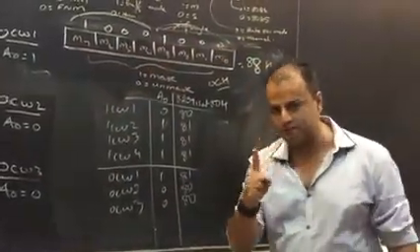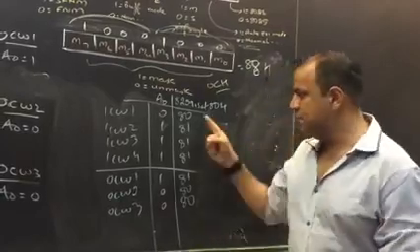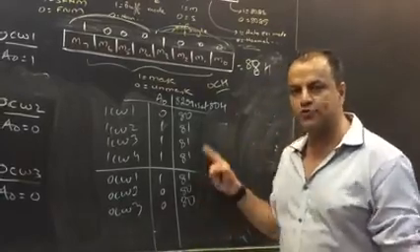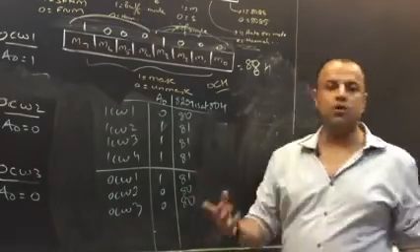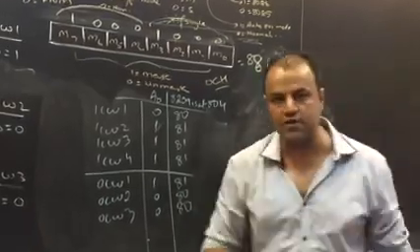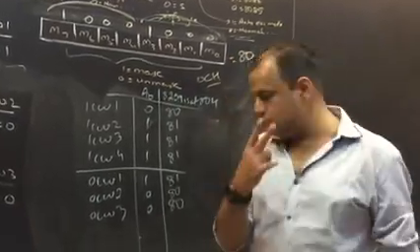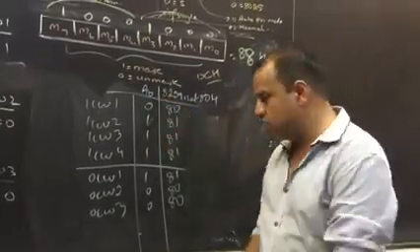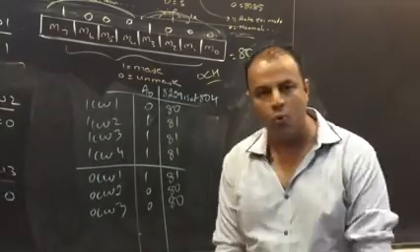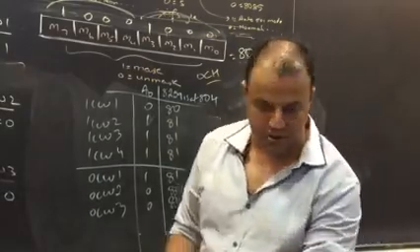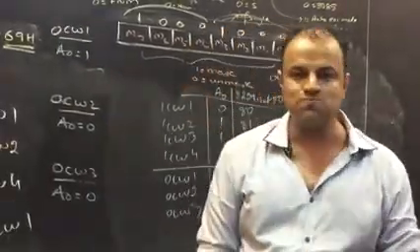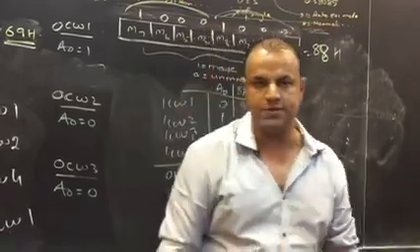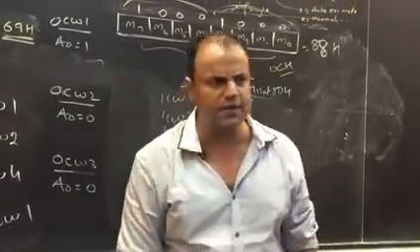Those were ISR addresses. That is a separate thing. Now I'm talking about the address of 8259. 8259 is one chip, but it consumes two addresses. What are the two addresses? 80, 81, or could be 40, 41, could be 42, 43, could be 84, 85. Basically, 8259 consumes two addresses. Those two addresses are being formed due to A0. Students say, why is this happening? Why this torture? No, this is not torture. This is mind-blowing intelligence. This is made so intelligently.